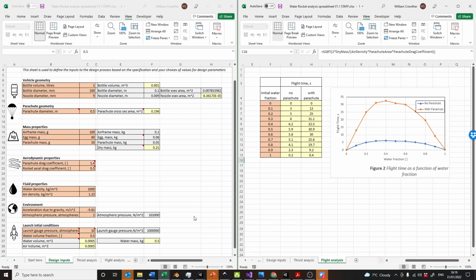The other things which you'd be interested in are the proper aerodynamics of the rocket. So on the way up, there's a lot of issues with stability. So does it actually point in the right direction? If there's a crosswind, what does it do in that? And if you're at the top of launch, how do you actually get the nose cone to come off? It's all very well having a parachute, but it's really quite tricky knowing when the parachute comes off and on. So those things we can't answer in a spreadsheet, but for that we develop a more detailed numerical simulation, and that's what the Unity simulation work you'll do later is for.